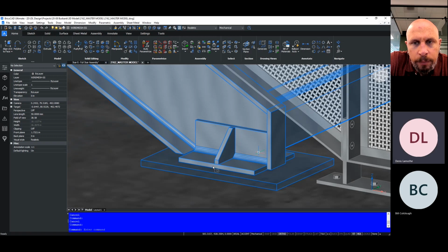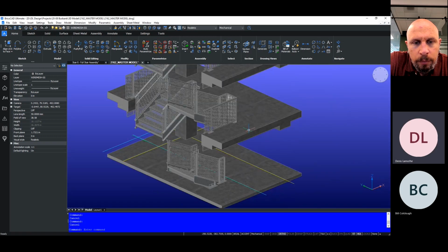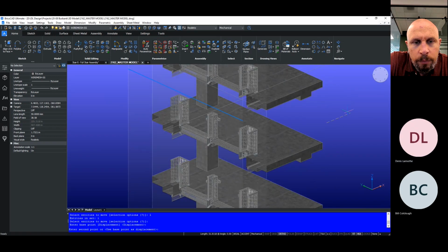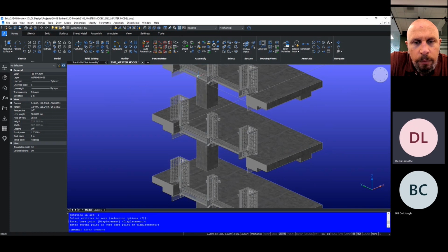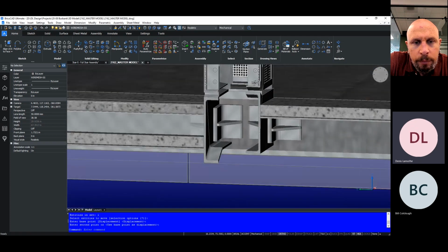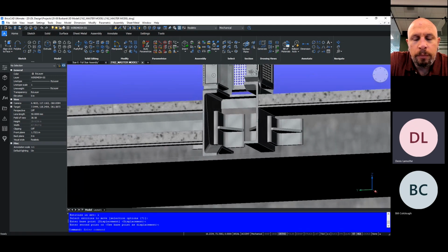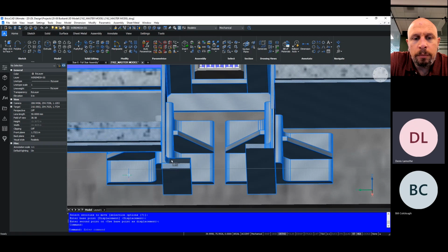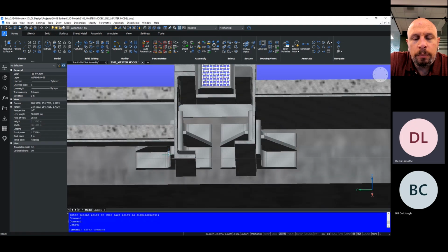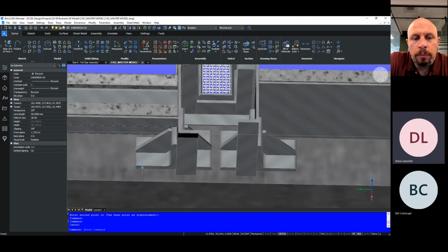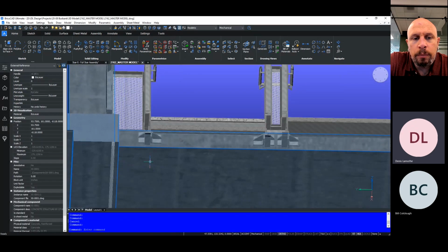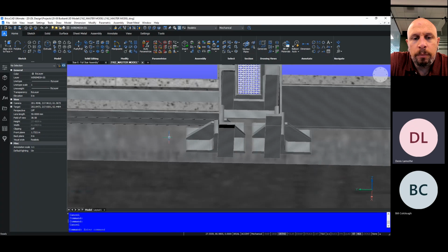These systems can also be used to attach to structure at the top of a stair. Just to show you a little bit here, this is a project called Burbank where we tie to a concrete slab. On either side of our stair stringer, we had these little clip angles on either side of our channel. And those would be welded to a steel embed plate, actually. We had this one solid formed. You're not seeing it on this drawing or the model, but it's there somewhere.